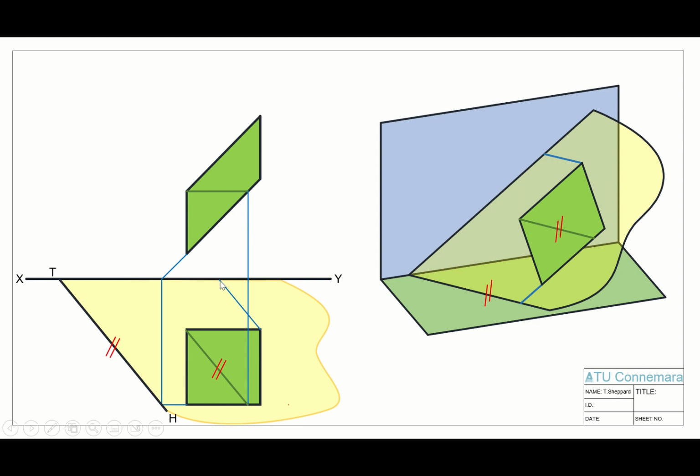That's our XY line in our plan view, our vertical plane, which we project up into our elevation, and our watermark line is going to look like a horizontal line in elevation. Why? Because our horizontal trace is horizontal in elevation. That's why this guy is horizontal as well. So that gives us our point on the vertical trace, which we then extend on, giving us the solution to our vertical and horizontal trace for our lamina. And that's method 2 then, finding our VTH.